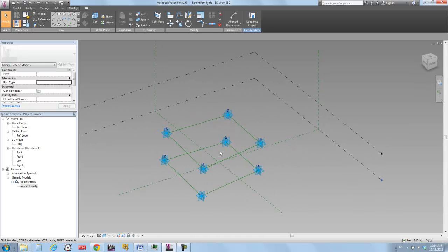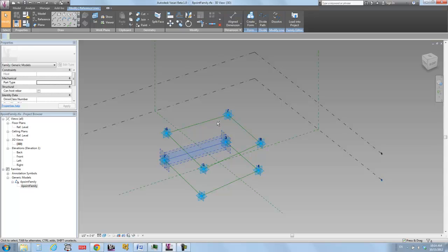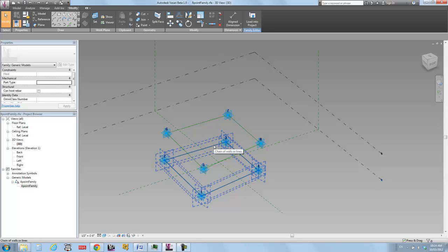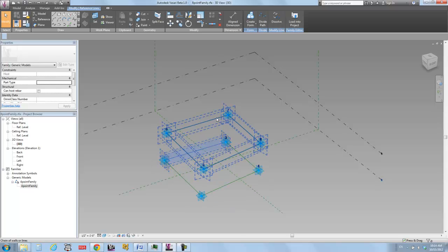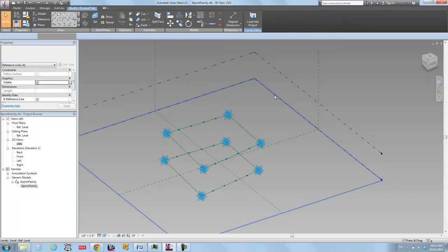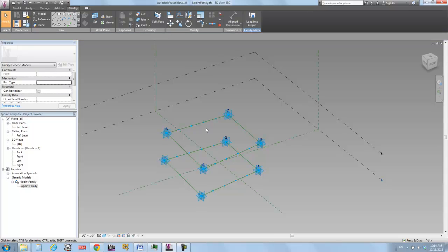I would like for everybody to select individual lines, not the whole loops. So if you tab select and tab select, so you just have these 4 lines selected, and hit Divide Path. What you're going to get is something that looks a lot like the divided surface, where you get those little nodal points, but they're just on lines.